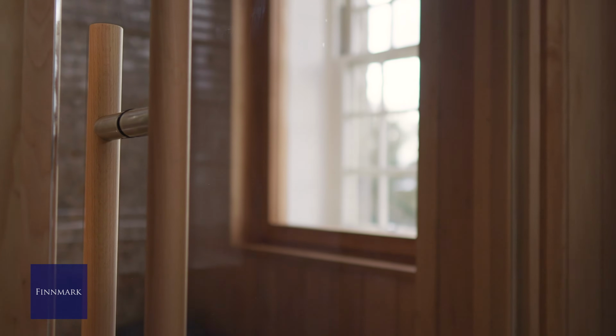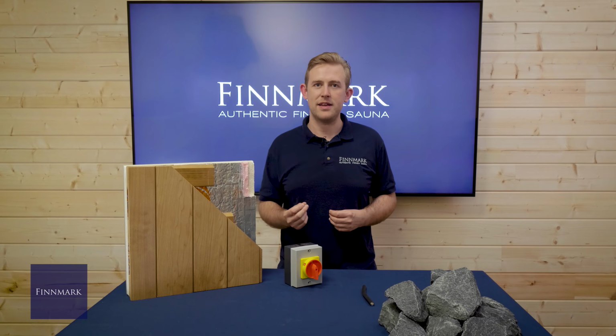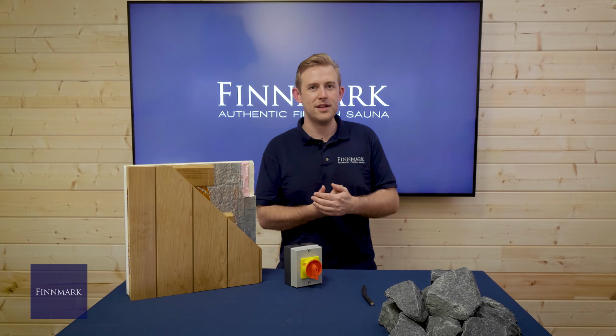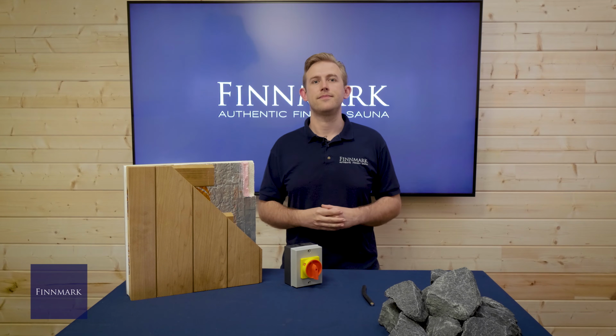The sauna door should always be specified as opening outwards for safety reasons, because if the user starts to feel faint, they can simply push on the back of the door to egress the sauna, rather than collapse behind the door, trap themselves inside and prevent any rescue.